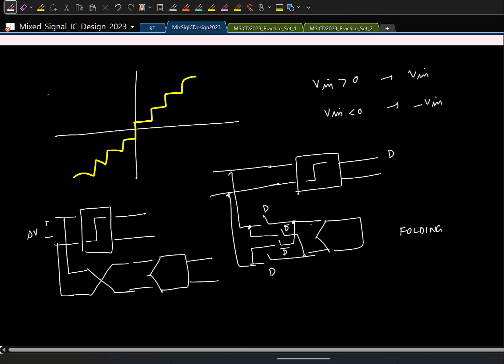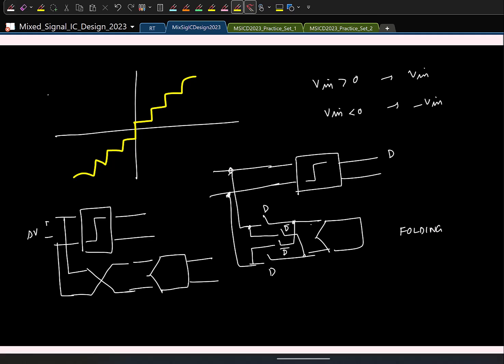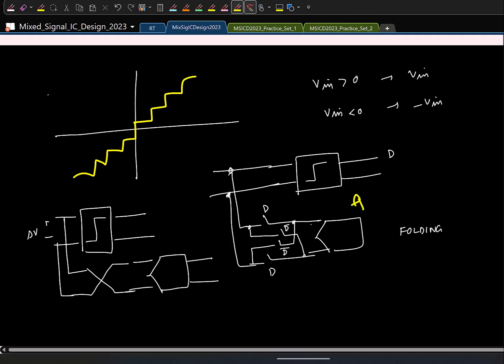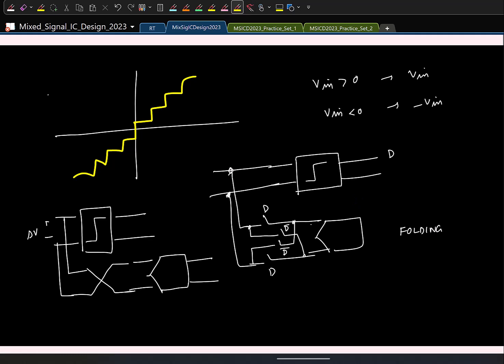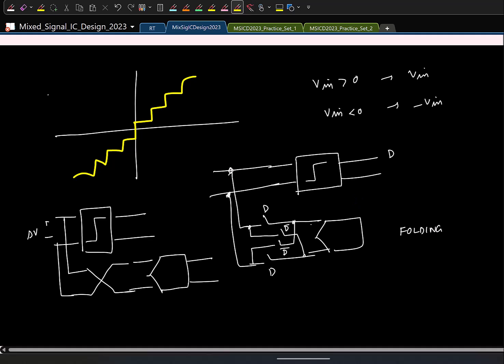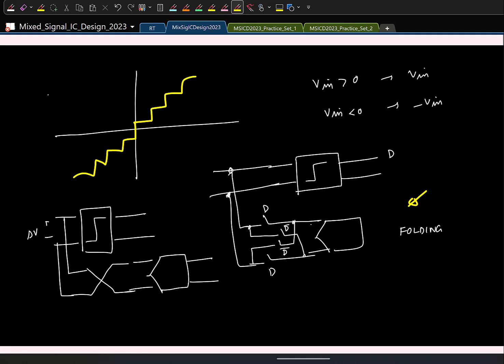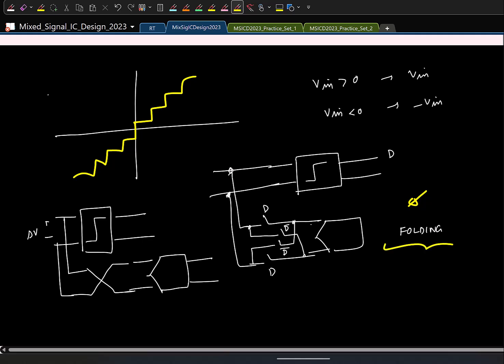Again, this was introduced in one of the olden papers, but it is not commonly done now because, as we'll see later, you can do a much better version of this, and that's called pipeline ADCs. We'll come to that later. But again, the same principle of folding, just like how interpolation was initially started with voltage and people did it in time, in principle you can also do this folding in time, and people have also done this.